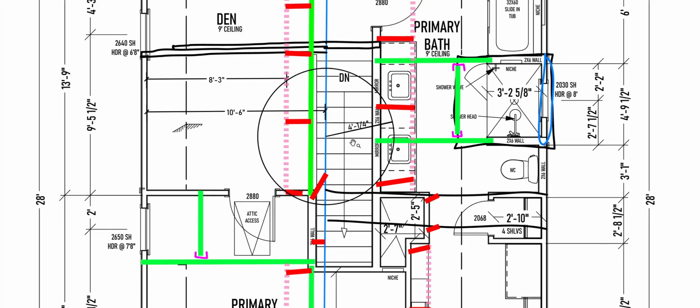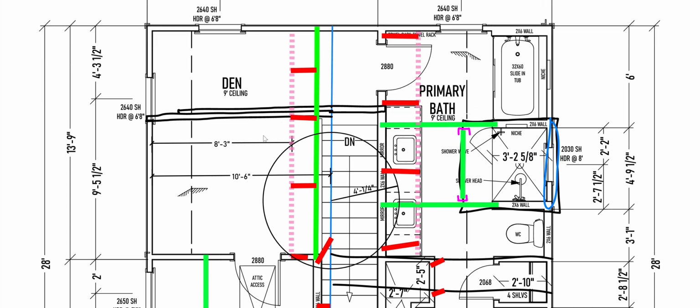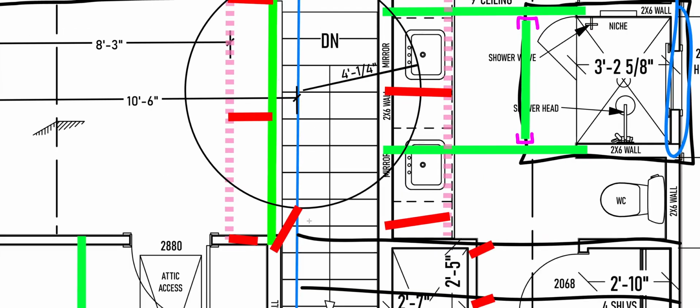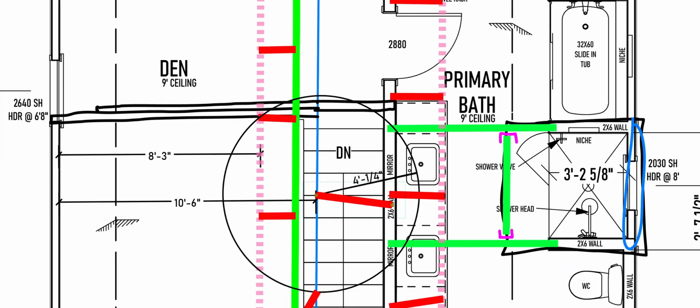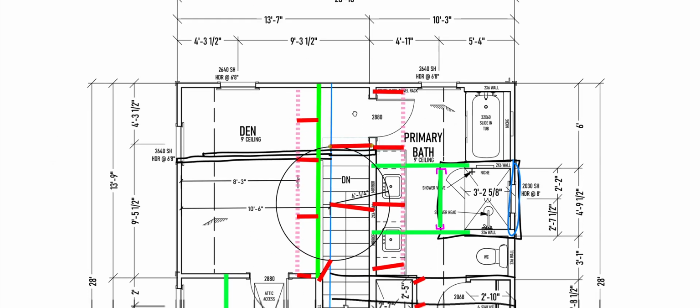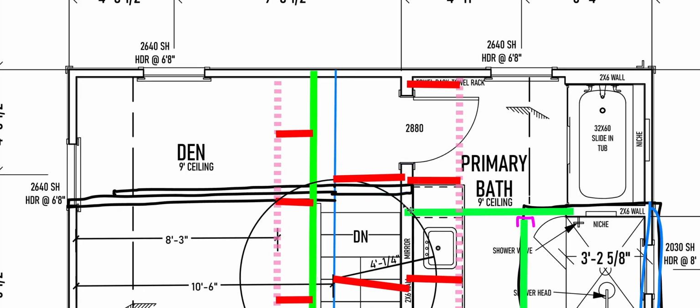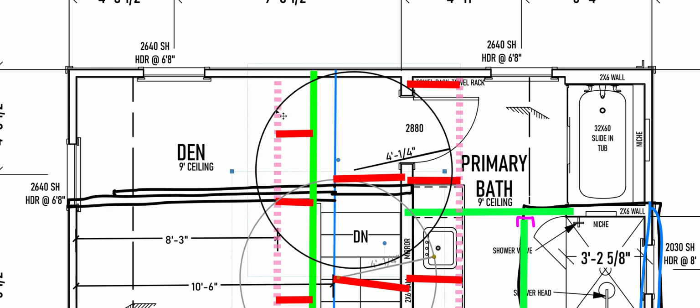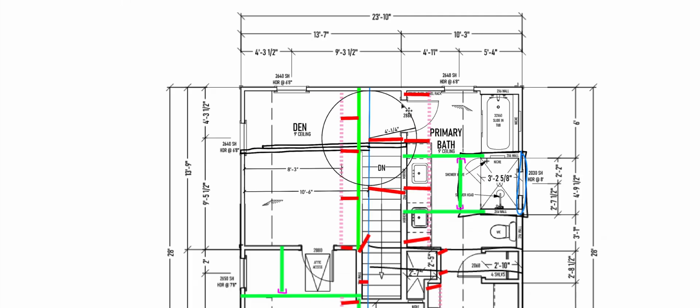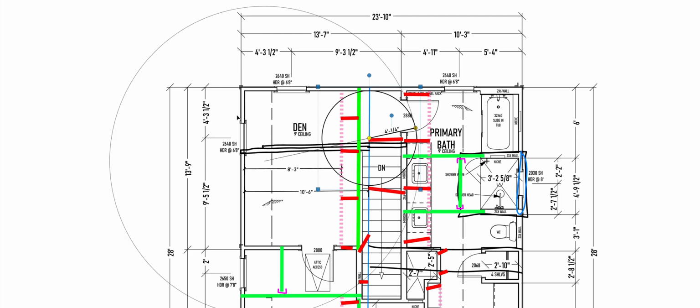So I know I can brace to it without violating my 4-foot rule. So 4 feet down the ridge from the last support is here. Add another one here to the wall, and the ridge is supported inside the wall, so I'm not concerned with that. And that's about a 4-foot spacing, so I'm happy there.